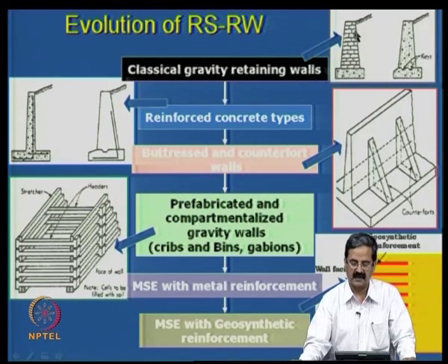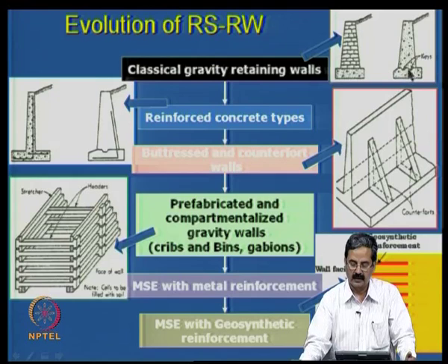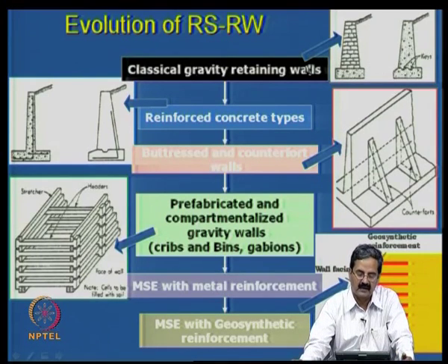So that is the concept of a gravity wall, in which you try to have some geometrical proportions in such a way that it will withstand all the pressures, both lateral pressures and the vertical components of pressures. So we design this, and sometimes when it is required, we try to provide shear keys also to increase the shear resistance, because when there is a lateral force acting, there should be some sort of resistance provided. Either it can be a shear key here, or even at the bottom sometimes. So that is one concept for gravity retaining walls.